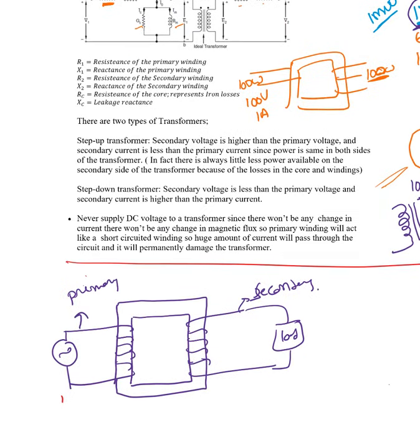So here this is V1, the number of turns on the primary, the number of turns on the secondary, and the induced EMF here E1, induced EMF here E2. So for the ideal case, ideal transformer, V1 equal to E1. Okay, there are no losses. So whatever the supply voltage is appears across the inductor. Same thing, E2 equal to V2. V2 is right here. And here is I1, here is I2.